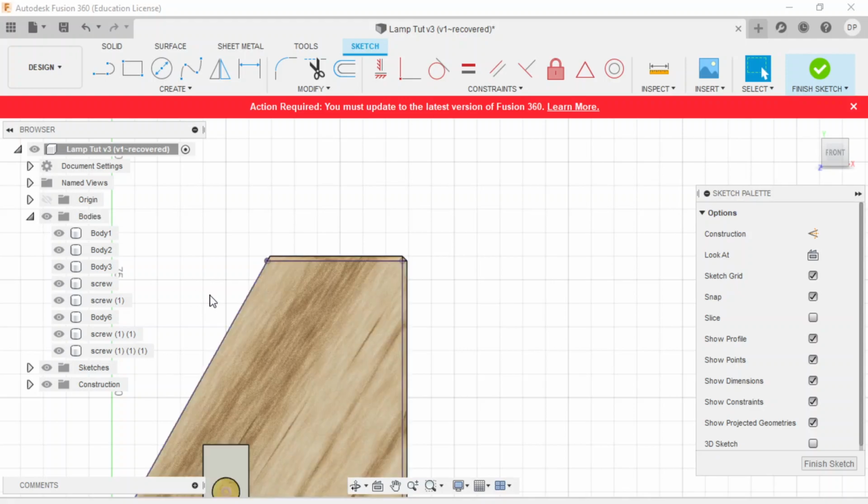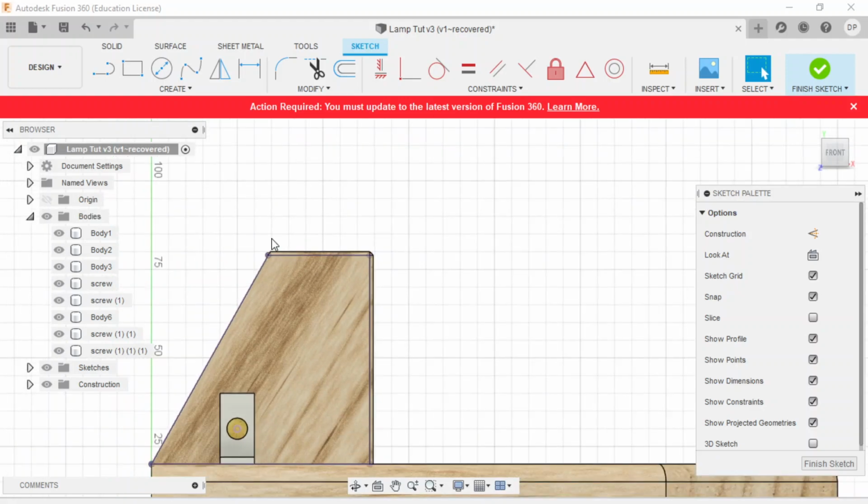Purple lines in sketches mean there are lines in your sketches that you didn't make. They were from another part in the design. So you can't adjust them. But if you were to adjust the height, like how I was showing you last lesson, you can change your dimensions and your whole job will change. They will affect the other sketch.